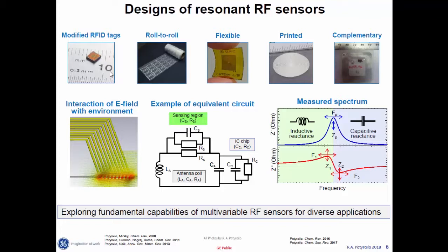In one embodiment, as I mentioned, we put a sensing material onto those antennas, and then the properties of the sensing film that are changed because of the gases in the gas phase affect the LCR properties of our circuit. And the second embodiment, that will be the example of liquids detection. We are detecting the properties of the liquid itself because this field propagates a little bit into the out-of-plane of this antenna structure.